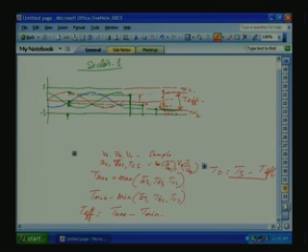Now, we want the time period in positive, that is during which we have to see, from here to here for the leg. If you take the inverter like this, A, B, C, this is our VDC. So, for the A phase, let us say this is A, this is B, this is C. Till this period, we want the top switch on. But if you see here, we are starting from here. A phase is only this much period is negative. So, what we want, shift the whole thing to the positive side.